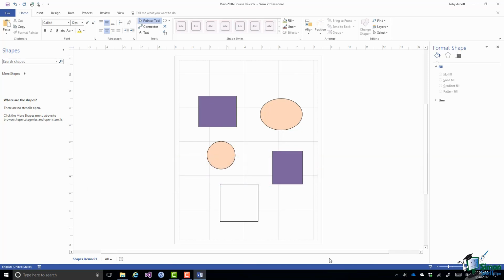One other thing to be aware of in relation to multiple selections is that if you do them using, for example, Area Select, let's go for Area Select, that's the rectangular one again. Let me draw another rectangle to make a selection, but notice that that square is not totally within the selection box, the Area Select box. And you'll see that it's not actually part of the selection.